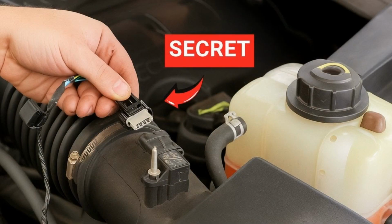The problem may in fact be with the speed control module itself. The mechanic should test this to make sure it conforms to the manufacturer's specifications. If it doesn't, it will need to be replaced. There is also a possibility that the problem lies with the switches for the cruise control system. Depending on the make and model in question, these may be on the cruise rod, or located at various points on the steering wheel.